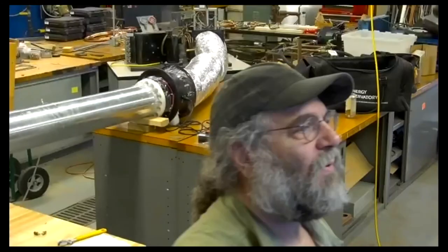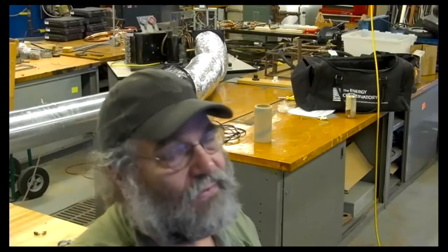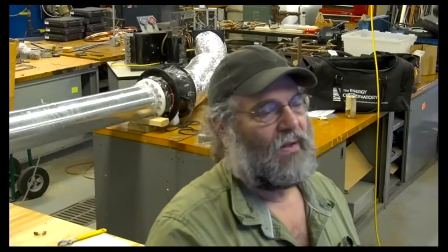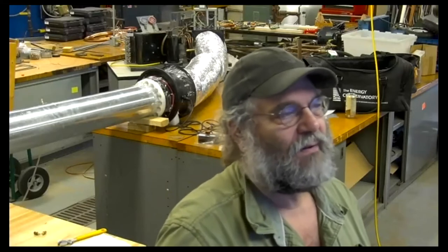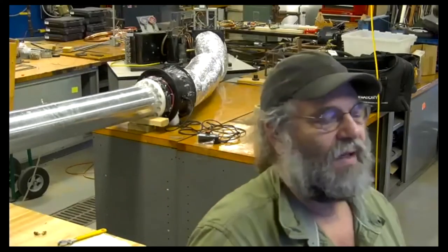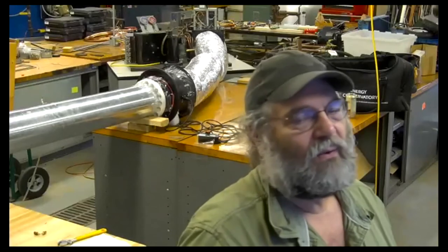Well, we are still struggling a little bit with hardware. We ended up with our differential pressure sensor wasn't such a hot deal. It was in the center of the VAV box, and we had the radial fan right in front of it, and we couldn't figure out why we weren't getting any differential pressure until I realized there isn't any flow out of the middle of a radial fan. So we now have 6 feet of duct, and we're starting to get some movement in there, but it wasn't lining up terribly well with what we would expect given using the function.